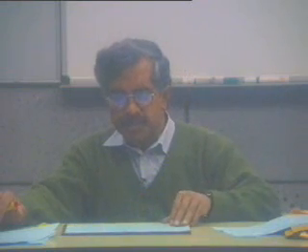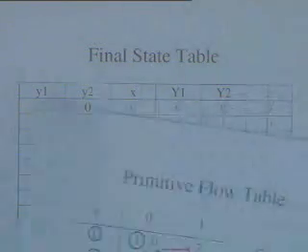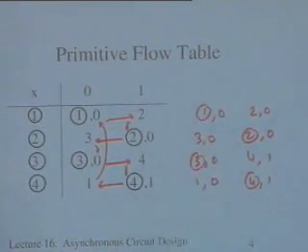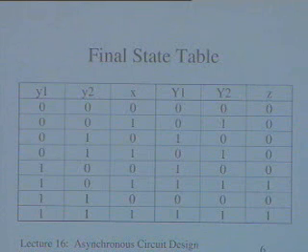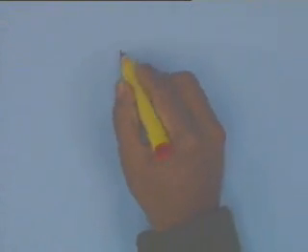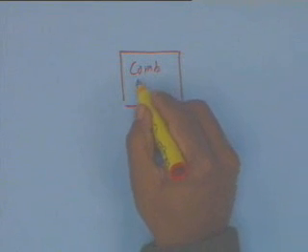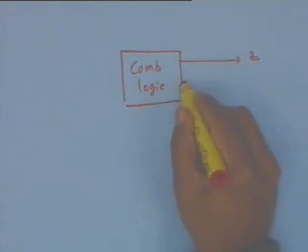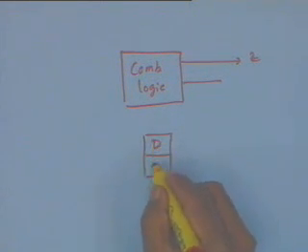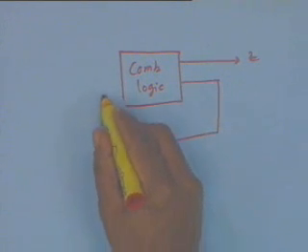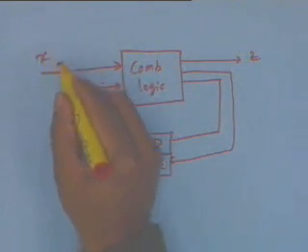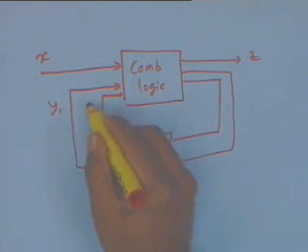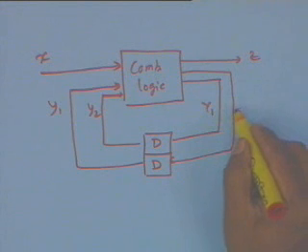So the state table is simply what we had before; I just have to replace the states by the proper encoding of the states and write it as inputs and outputs. The idea of writing this as inputs and outputs is to get the specification of the combinational logic block. Because after all, the model that we have over here is this combinational logic, the Z output, and of course now we have 2 inputs. And this corresponds to y1 and y2, the excitation y1, y2.